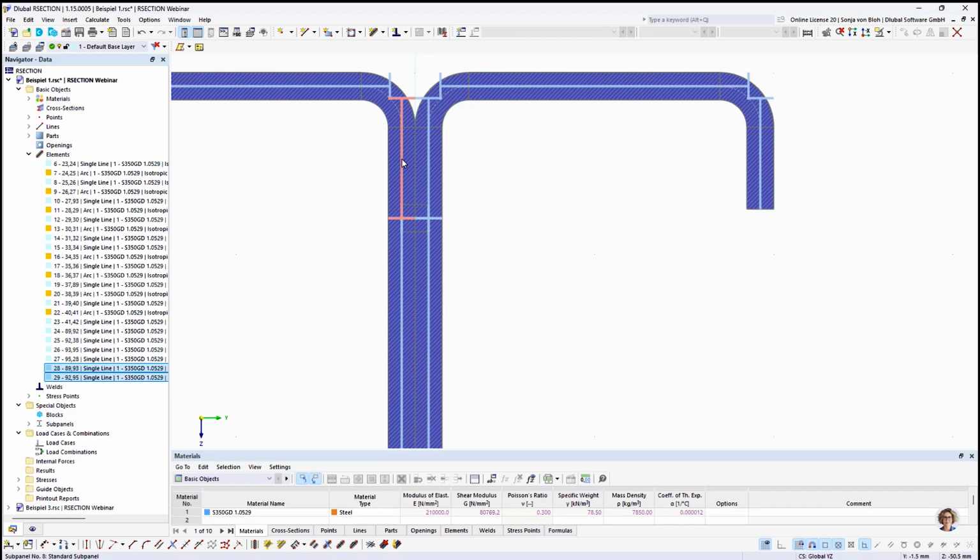First, the screw elements now contribute to the calculation of the cross-section properties, even though they are intended only to represent the connection between the sections. Second, the design of the cold form cross-section is no longer possible because the cross-section becomes branched at this location.